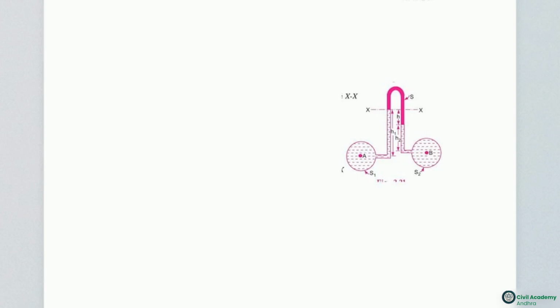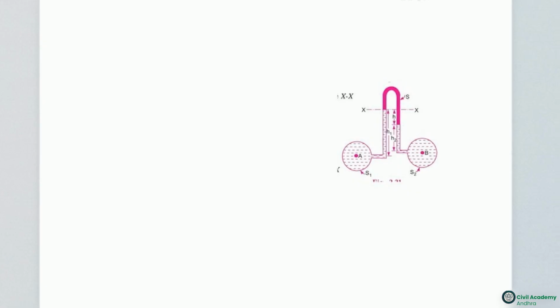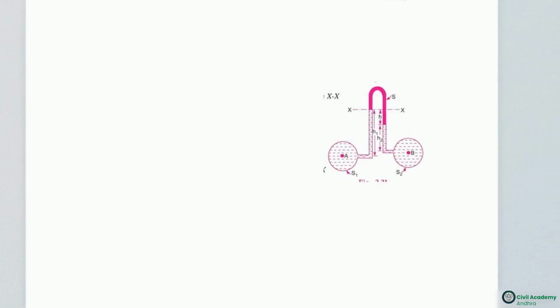Sometimes engineers need to measure very slight pressure differences between two pipes. This diagram shows an inverted U-tube manometer, which solves this by using a very light fluid, like trapped air, at the top of the bend instead of a heavy liquid at the bottom. This setup introduces a specific trap. Because the measuring fluid is trapped at the top, our standard datum rule flips. You must draw your reference line at the highest contact point between the liquids, not the lowest.